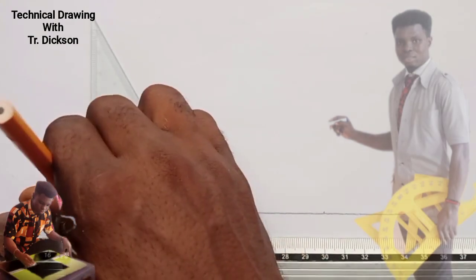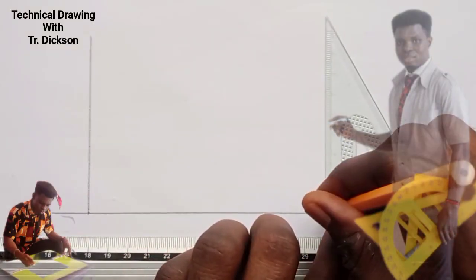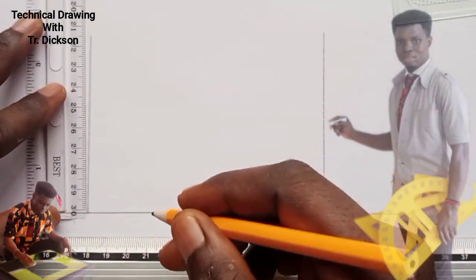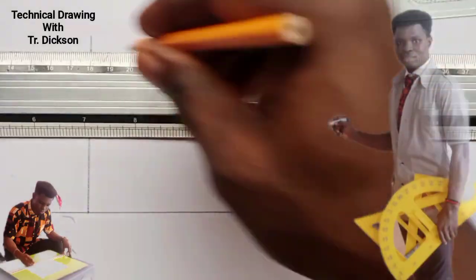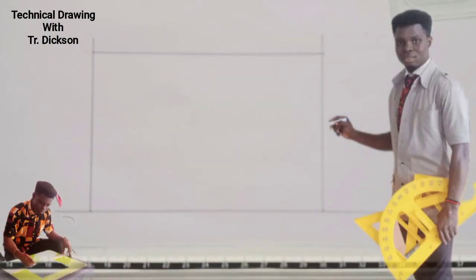And then I will want to take my vertical, and that is the breadth to be 80 mm. So I'll first of all draw a vertical line at this point. And also with the use of my set square, I draw another vertical line here. Having drawn that, I will take the measurement using my ruler. Remember I said 80. So 1, 2, 3, 4, 5, 6, 7, 8, which is 8 cm. That's 80 mm. So at that point, I draw my upper horizontal line. All right, that has given me a squared rectangle.